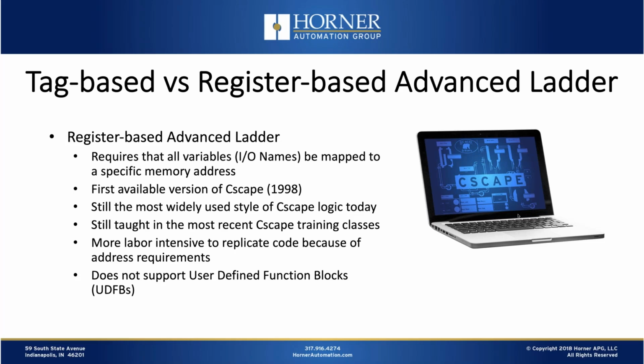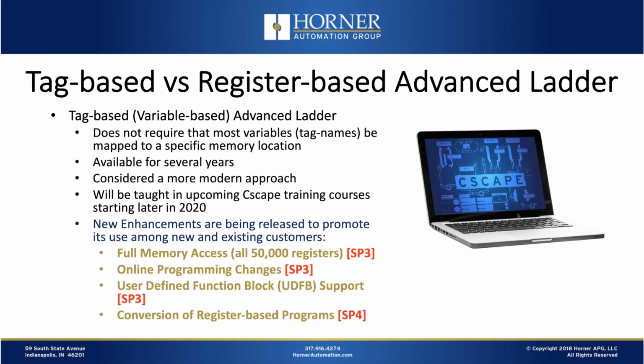It's just a modern approach to that sort of code utilization that, again, is not possible with register-based advanced ladder. Now, when we contrast that with tag-based or variable-based, we use both those terms interchangeably. So we'll say tag-based advanced ladder, sometimes we'll say variable-based advanced ladder. It's the same thing. We use those two terms interchangeably.